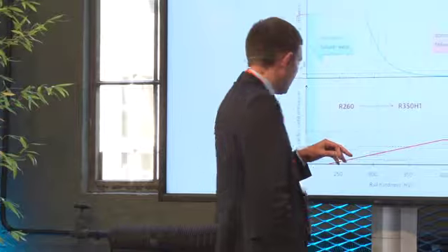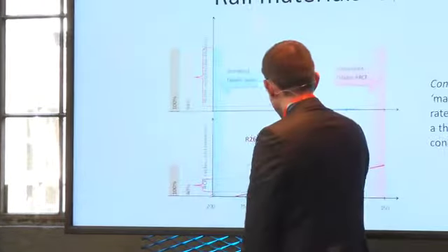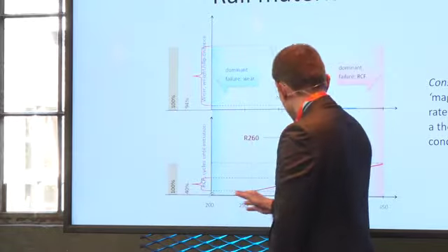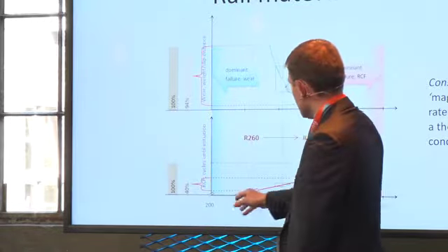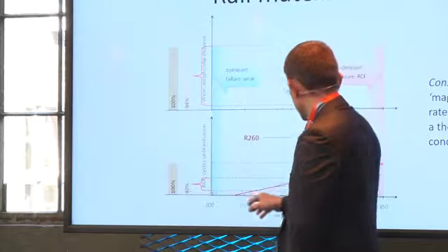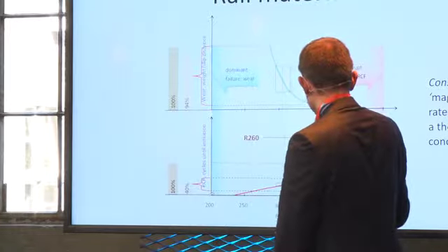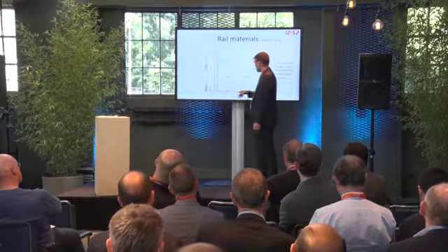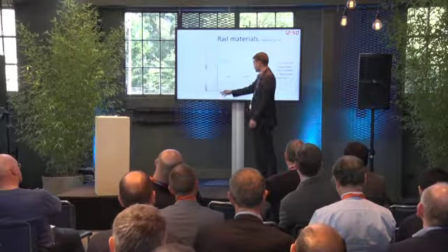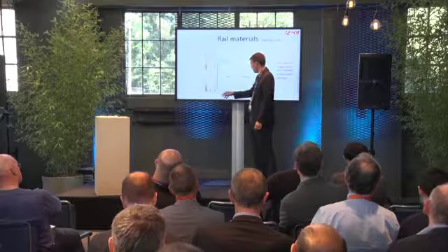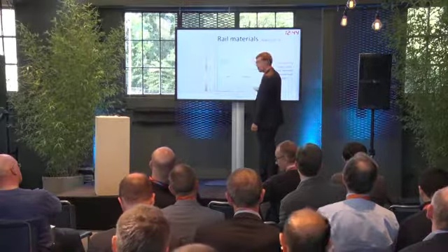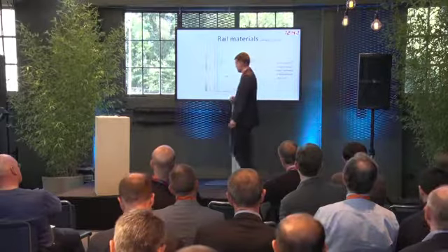Well, when you compare these two graphs, I should first say something else. On the horizontal axis, you see the rail hardness, and I limit the values from 200, in this case, to 450, and that's about the values that are achievable nowadays. So in old tracks, there are still some 200 grades, and some companies are talking about developing rails in this area.